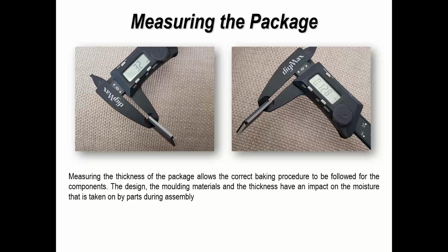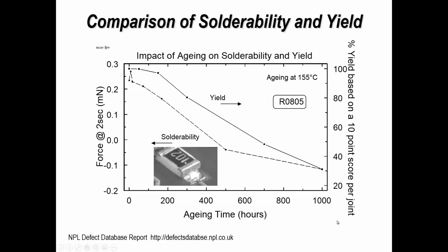Now, another little trick that can be used if you're evaluating components, moisture content, soldering, etc., and seeing if the parts change dimensions, you can in fact measure them. This is not the most accurate way of doing it, but it can help if a component is particularly sensitive to moisture and soldering, and you see a change in the package. Any measurable change potentially can cause damage to the part's interconnection inside the package. So whatever tool you might have is better than nothing at all. It's not ideal, but it's something that can be done to measure changes in thickness.